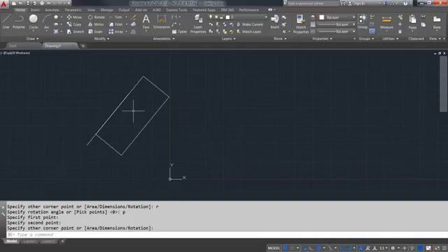And we got a few other quick questions we can touch on here. So next one is, can you pre-select the printer you wish to use instead of selecting from the drop-down menu? As far as I understand, that's page setup, is that not? Saving out your page settings for printer and what CTB you're using and page sizes and whatnot. Right, page setup can be pre-configured and it can be embedded into your templates from which you then would start every new drawing. And as long as you do that, then your page setups will be there and available.